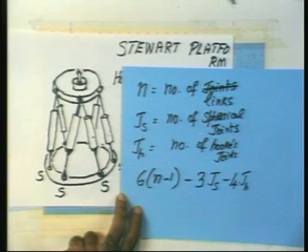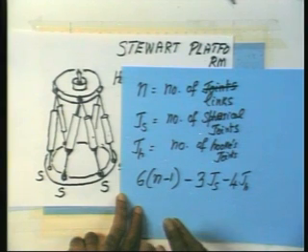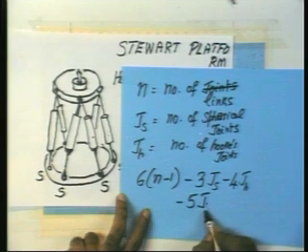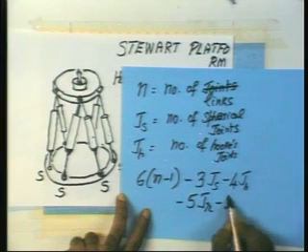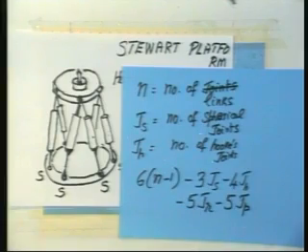Now what about the revolute joints? How many do they remove in space? A revolute joint has 5. So minus 5 into J revolute, minus 5 into J prismatic. This is the entire formula. Depending on the joints, this is for the degrees of freedom in space. Let us apply it to the Stewart platform. Let us go back to the Stewart platform and apply it here.